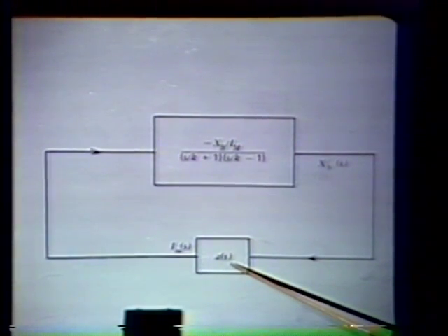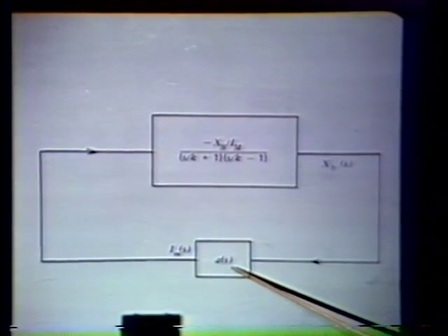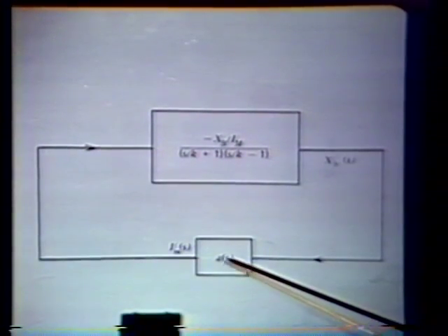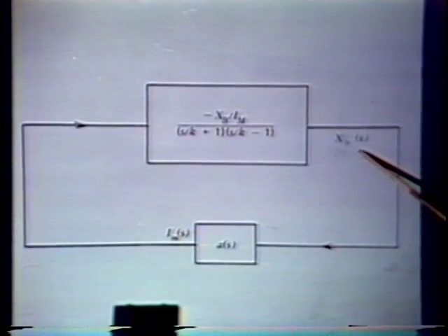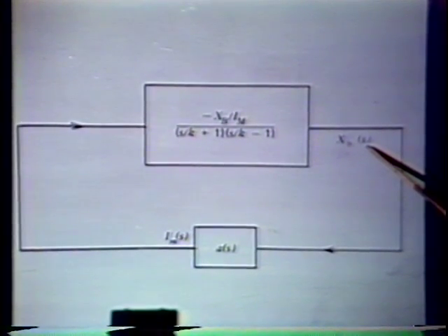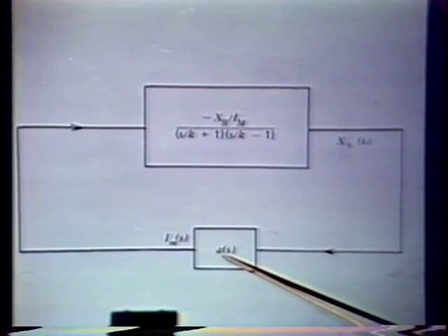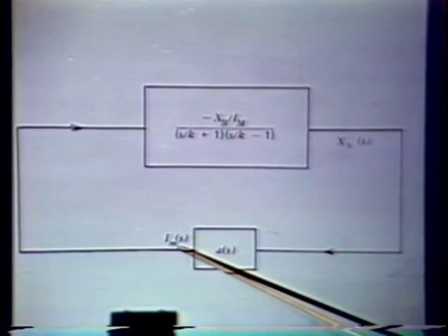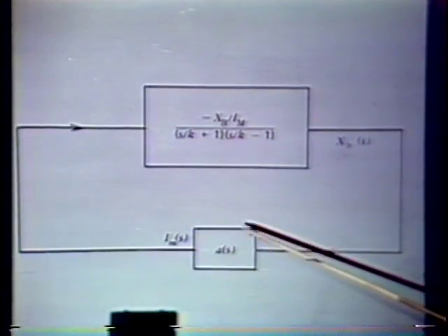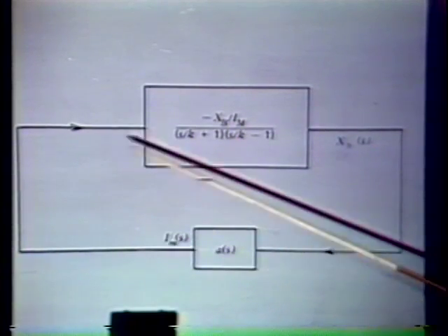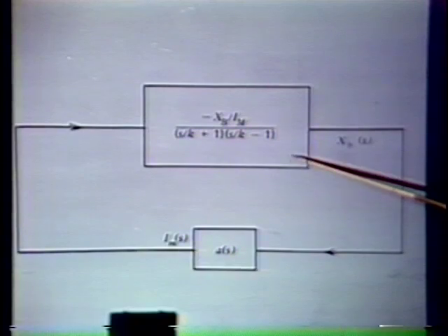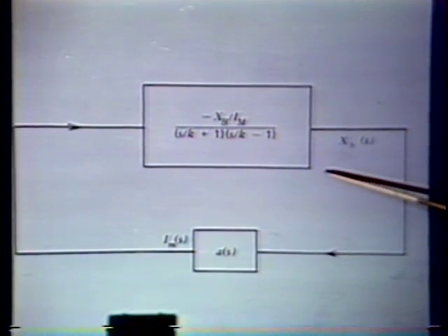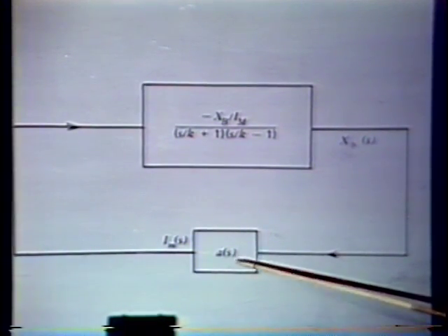We'll find out that we have to add some compensation. We operate on the electrical signal proportional to ball position with our amplifier, and the output of the amplifier is magnet current. So this completes our overall loop. We complete the loop by surrounding the ball dynamics with our amplifier.